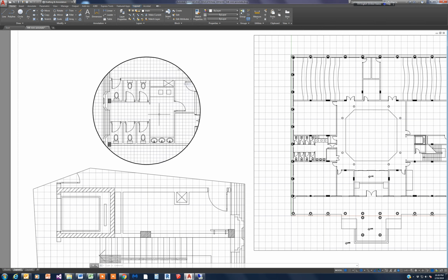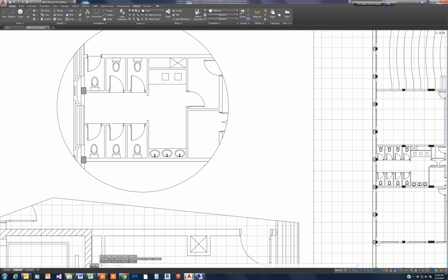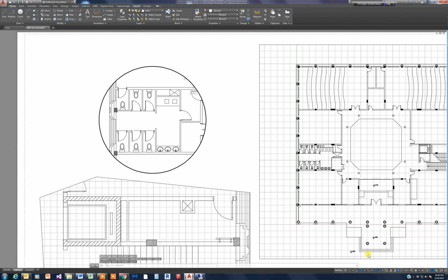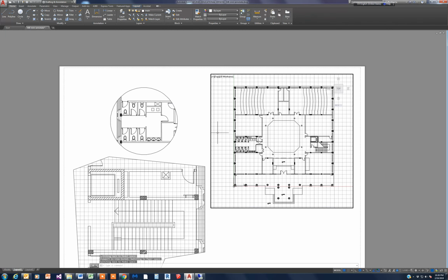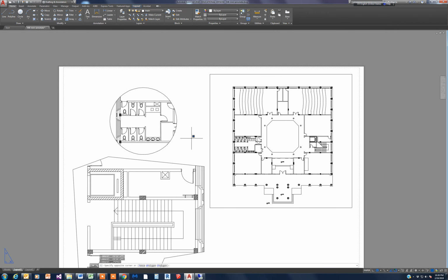Now the first thing I would like to do is hit F7 to make it look like a sheet. I don't want to see the grids from AutoCAD. And this is locked. I told you last time to lock every time. If you look here, this is locked, because if it's not locked, then I will lose my scale if I zoom in and out. But now I'm zooming in and out without affecting my scale. My scale stays as it is. Yeah. So what we're gonna do today, I'm just gonna go to this one and do F7 as well, and I'll go here and hit F7. So now it looks like a sheet.